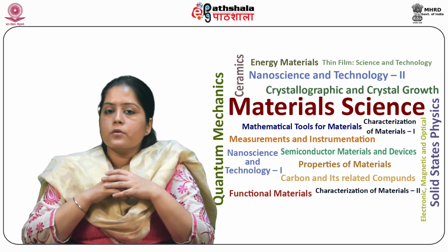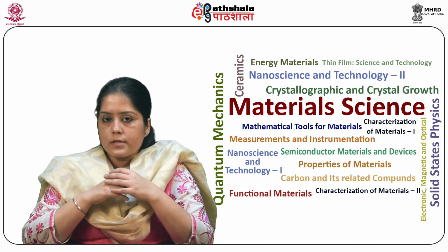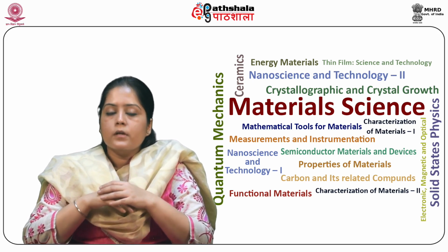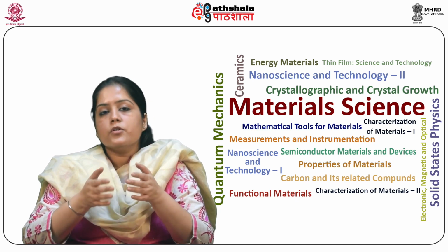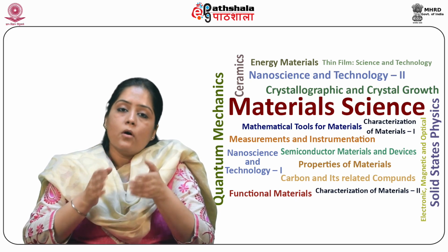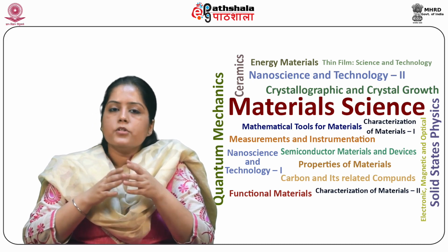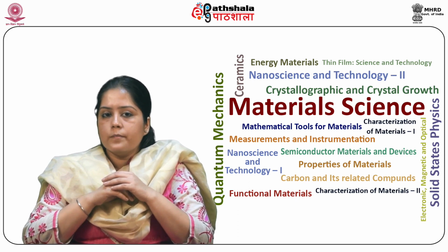High absorption coefficient greater than 10^5 cm^-1 with a direct band gap of 1.5 electron volt. Junction formation ability. It should have high quantum efficiency, long diffusion length, low recombination velocity. It should be abundant, cheap and eco-friendly material.